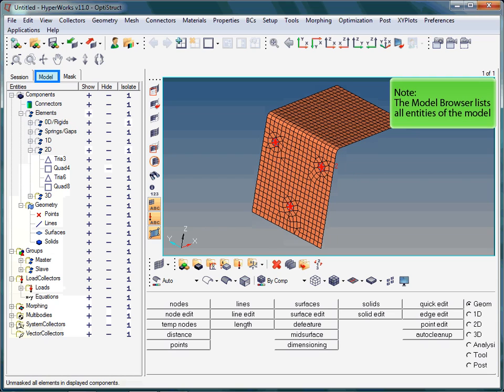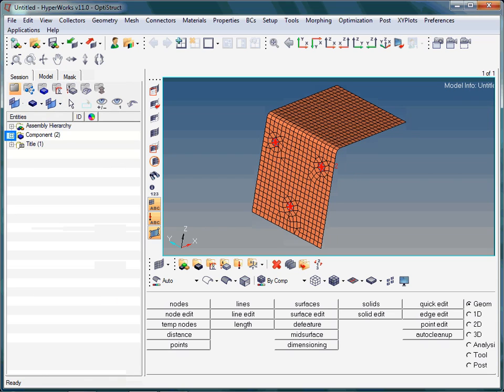Please click the Model browser tab. Now open the component folder. Please notice the symbols next to the component named LMFL1. Hopefully, you recognize these symbols again. The one highlighted refers to the finite element mesh, whereas the other refers to geometry. This should already give you the answer to the question, what are components about? Components, or component collectors, host information about the mesh and the geometry.